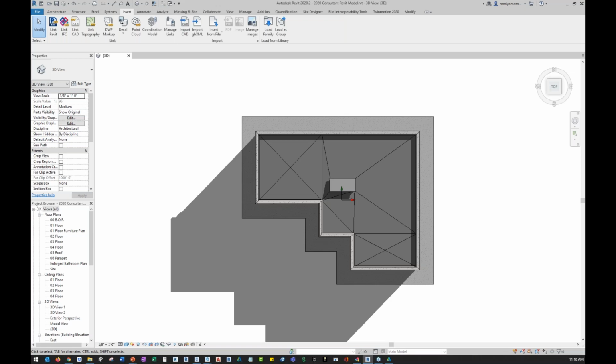Does BIM 360 do the file locking in Civil 3D? Yes, file locking in Civil 3D, that icon is directly tied into the BIM 360 portal. So when you open it up, the BIM 360 portal will realize that a file is in use, and the lock option will automatically pop up there. When the file is closed, it'll unlock the file.